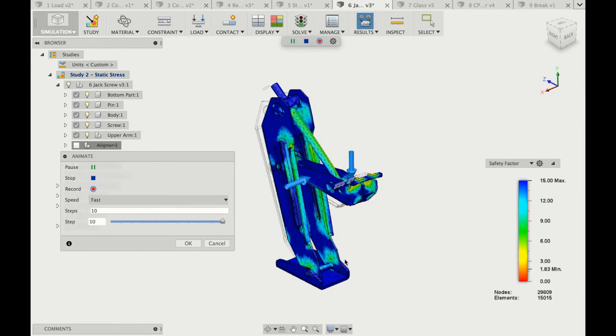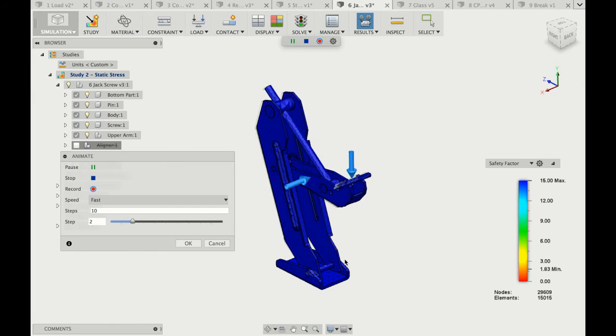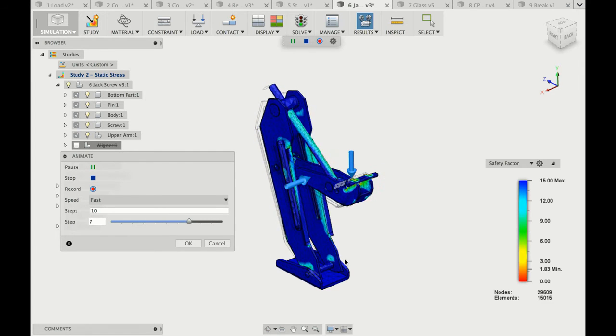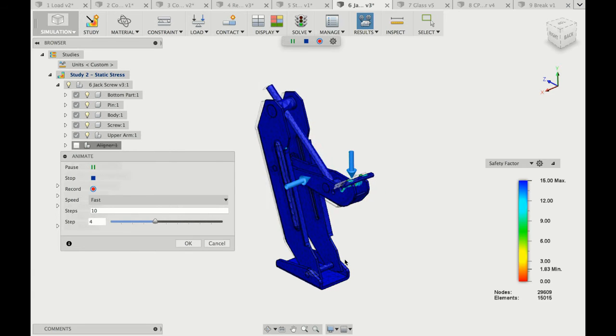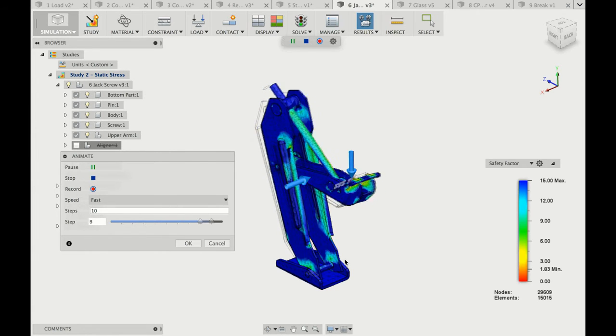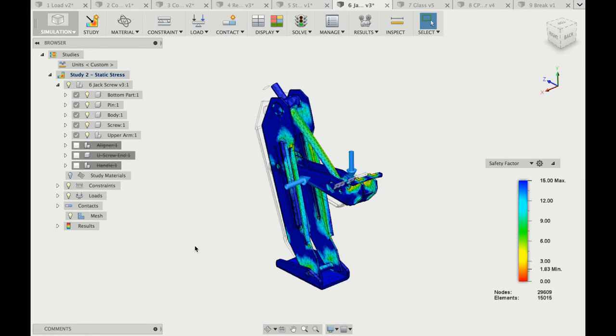So I think, actually, what we're doing here is just a linear analysis, right? So it's that one point in time, once it's been jacked up. If you look at something like Inventor, which has dynamic simulation, you can actually look at the process of jacking it up and then do an FEA study at the end to look at what kinds of loads were generated due to the motion as well as the weight of the car. And I think that would give you a more realistic picture of that entire process rather than just this one snapshot in time.